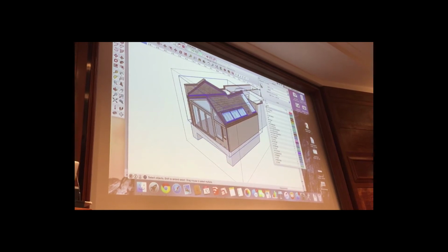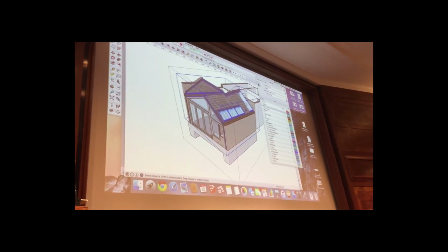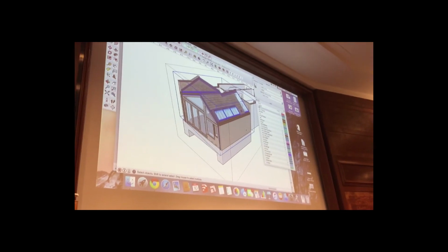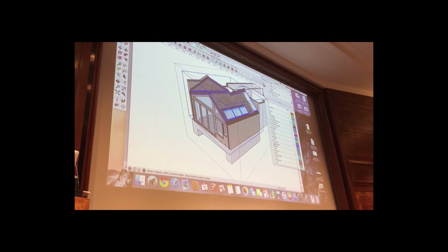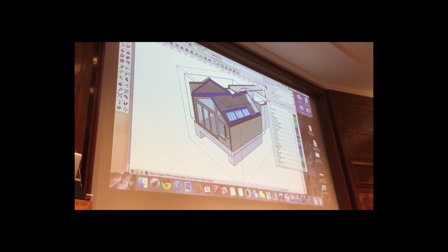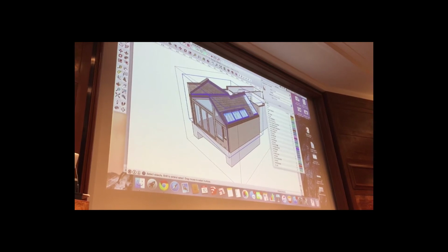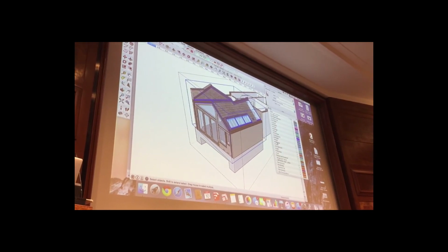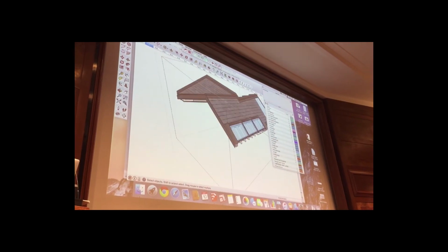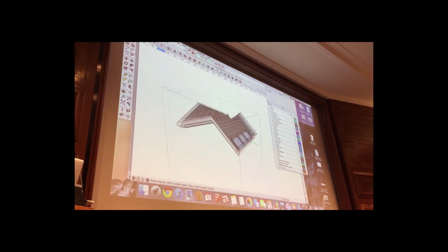And within each element obviously has a layer associated to it. I always prefix layers, just a note on prefixing. I would always prefix it with an A normally, because it comes at the top and it stands for architect. Very handy. And when we get deeper in, I'm going to simplify it a bit, take those slates out.